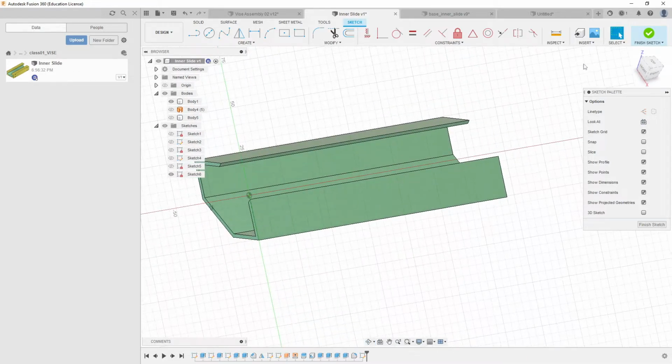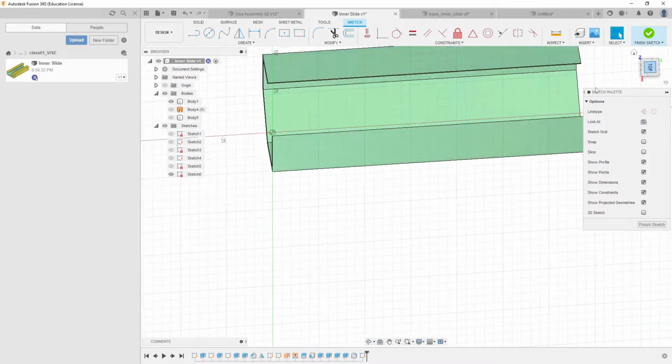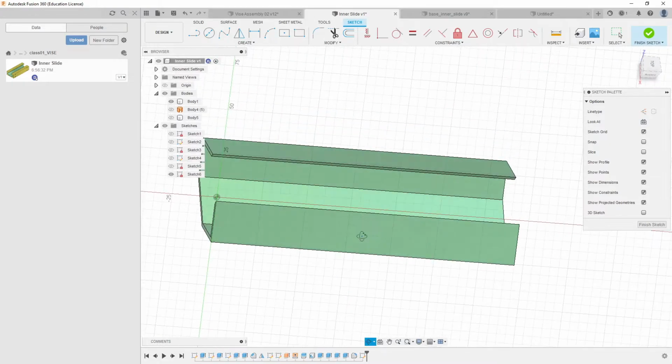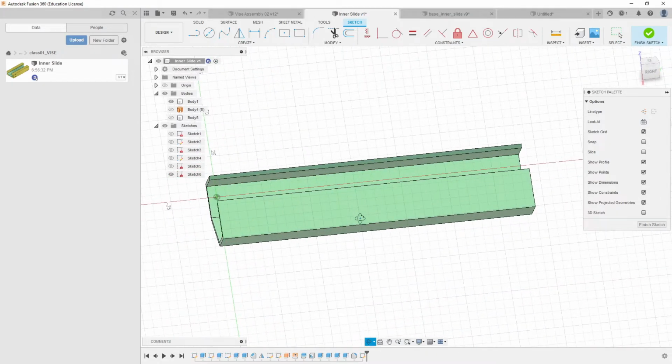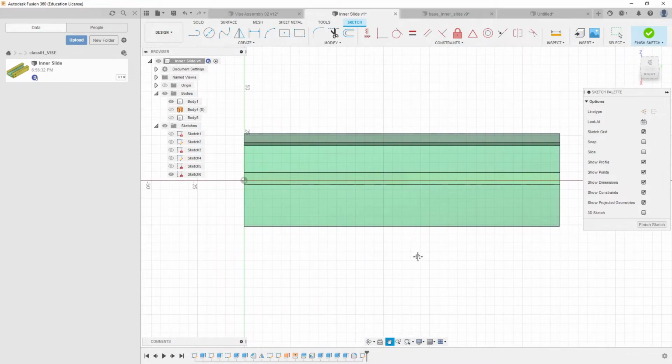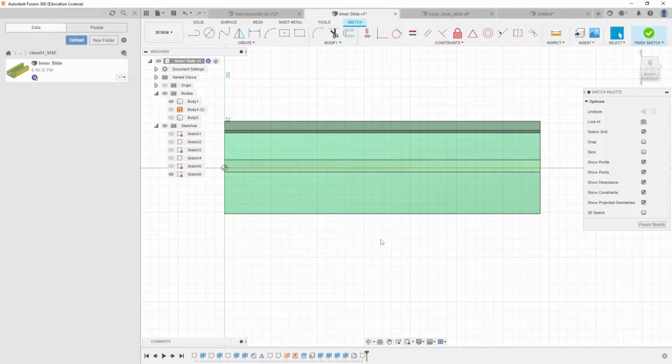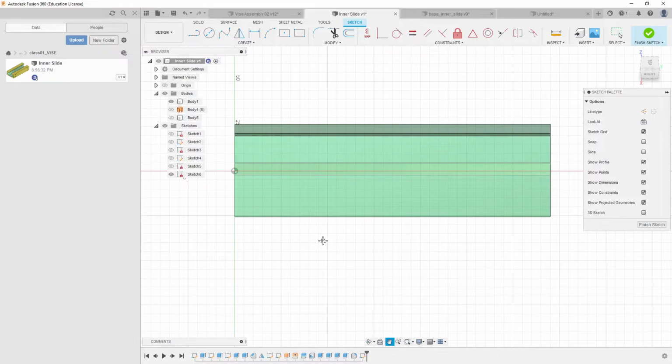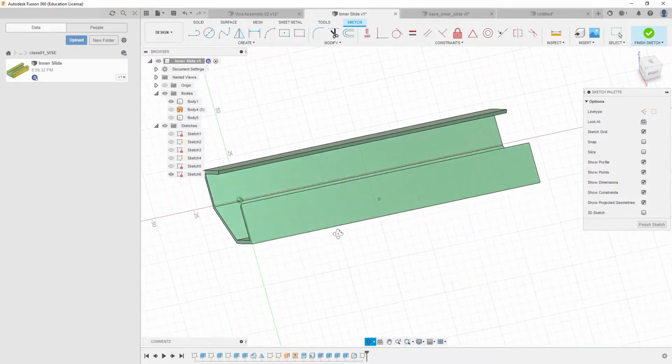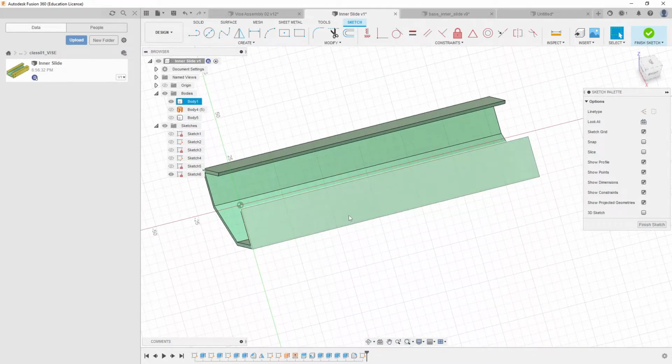And it makes things a little bit complicated because I don't have anything on this cube to line up to. So it looks pretty good, but that's not flat. So I might need to use a different tool down here, that's Look At, and it's this face here, and now it'll flatten me back out to this face, you see? It doesn't honestly matter if you're looking at it head on, and I would probably recommend that you get fairly used to working on a two-dimensional sketch plane at an angle, because sometimes you need to. Okay, so here's what I want to do.